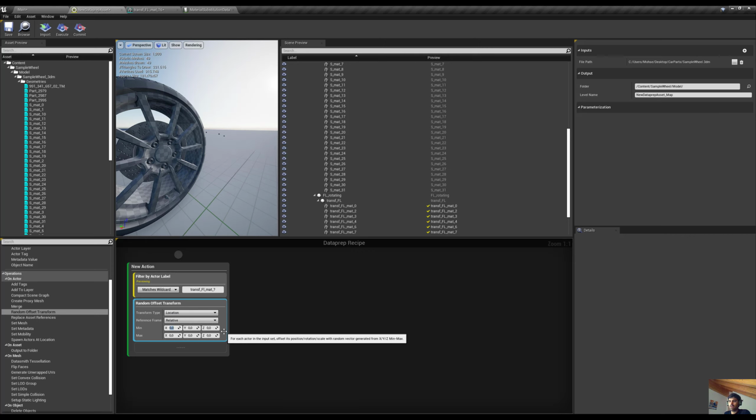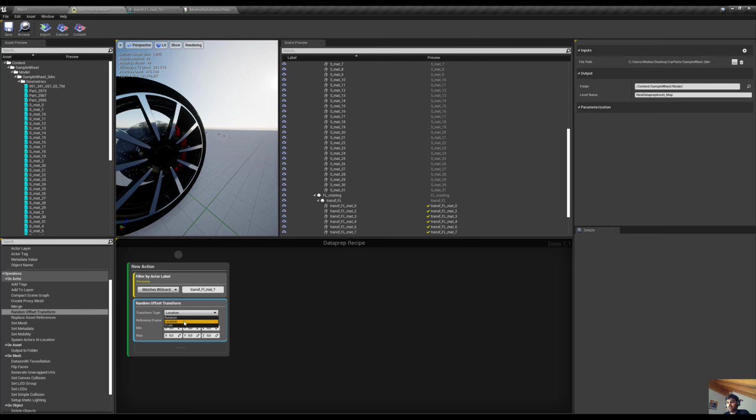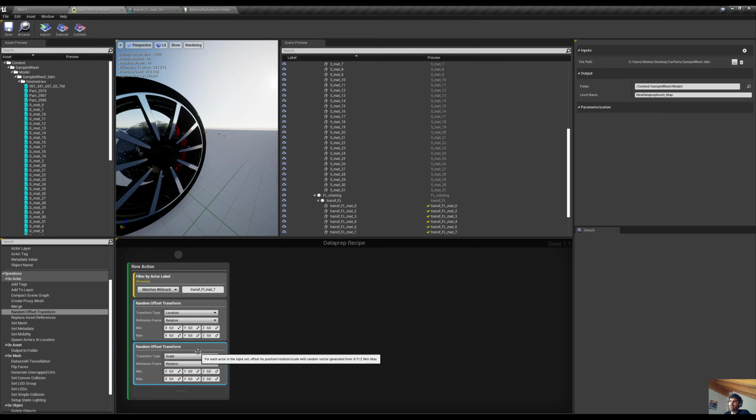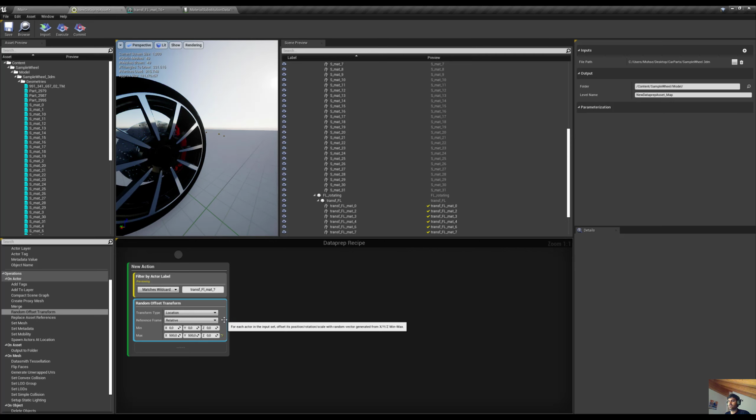So now random is going to give them a location. Just a location, sorry, but you can also put a rotation or a scale if you want, but you need to duplicate this one, for example, if you also want to influence the scale. So in the location, I can say something between 500 or 5 meters on the x-axis, and on the y-axis also 5 meters. On the z-axis, I do not want it, so I want to keep it horizontal. And relative or world, I would like to just keep it as world.